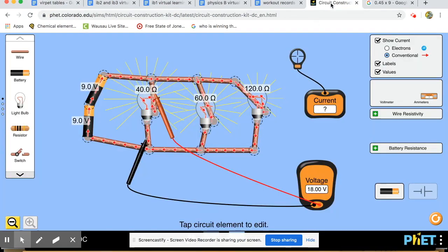What about resistor 2? Well, there's another loop here. This is a little bit bigger loop. You see this middle loop right here? That is another loop. And what that 4th rule or 5th rule says is that this loop also has to use up all of the voltage, 18 volts. Because voltage is the amount of energy per charge, each loop has to add up to the voltage of the battery. If there's 18 volts leaving, that means that by the time it gets back to the battery, all 18 has to get used up so it can get recharged again.